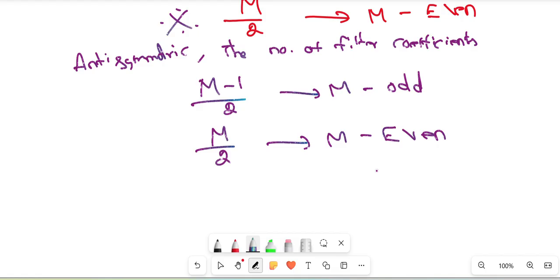So, FIR is a causal system, and how to describe the difference equation in terms of the Z transform, and how the convolution function with symmetry is limited to 0 to M minus 1 for the FIR filters, and how the impulse coefficients h of n are replaced with the coefficients bk.